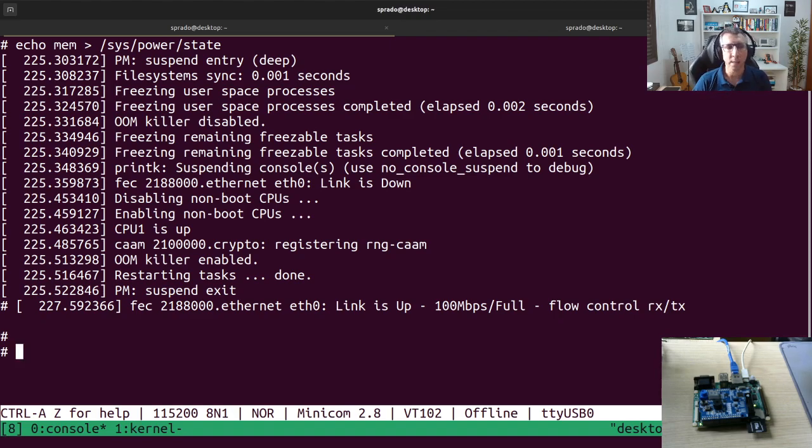That's one technique that you can use to decrease power consumption. You can by default get the system into a suspended state and configure a few wakeup sources, especially if your system is based on events and you don't want to be running the system forever just waiting for events. So you can just go into a sleep state and configure events from the system to wake it up. That's one nice feature provided by the Linux kernel.